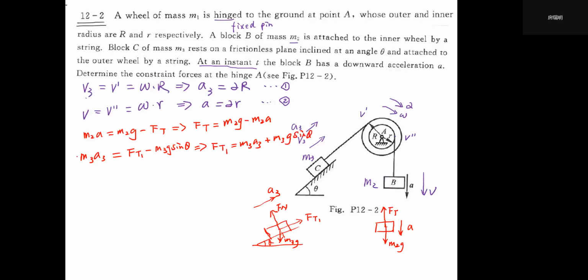See, after all this analysis, we can cut this. So from action and reaction force, Ft1 here, we also cut this off. We have this Ft here, and we try to remove this fixed pin and replace it with two actions, Fax and Fay, right?